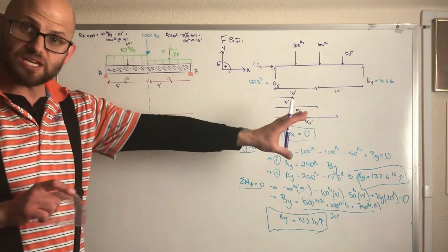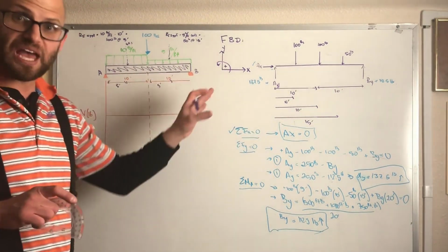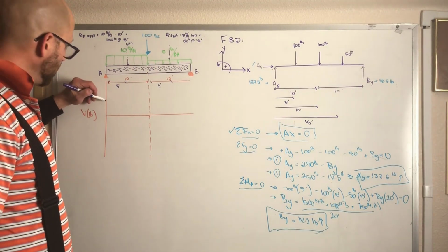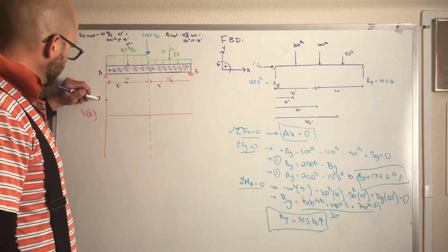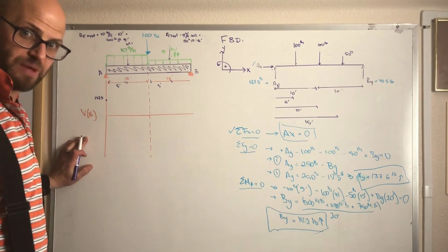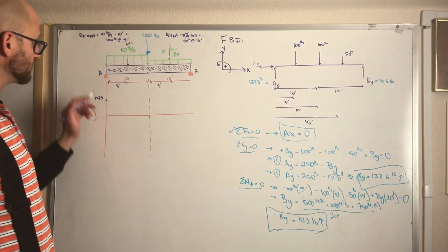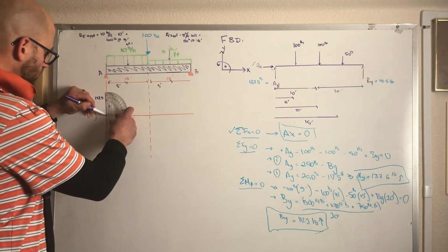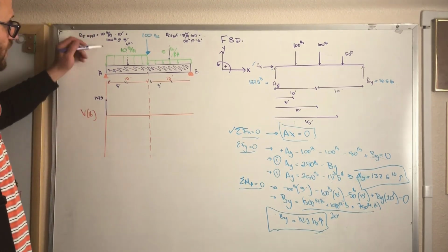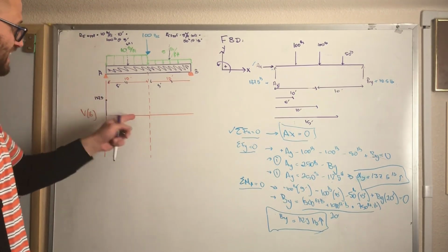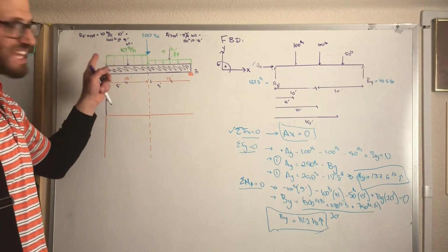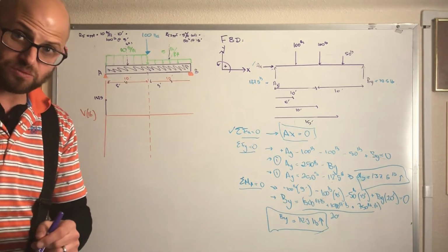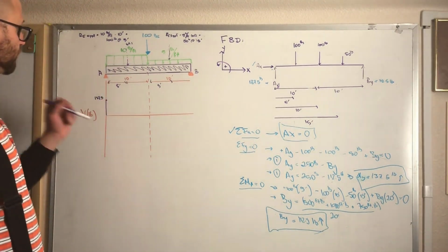I could just read my math, and then we have a story to be told over our shear diagram. So if we assume that this is 137.5 and we already have pounds in our y-axis, this is where our reaction starts. So this is the first thing that we see. Now we go across 10 feet and there is a constant negative 10 pounds for every linear foot.